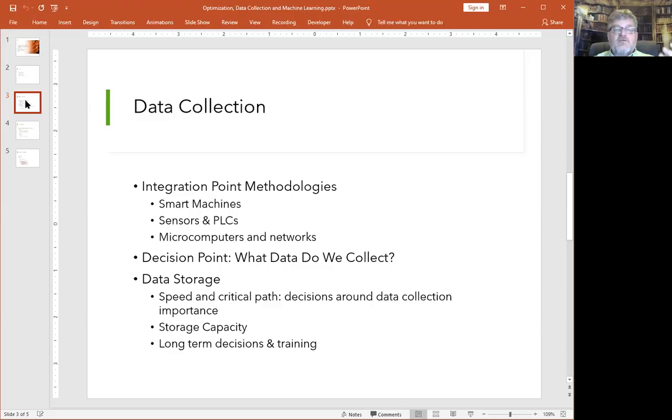So now, 6 months later, I can go look at all the data for every single crimp tool that followed that same exact image. In other words, the image matched, even if it was within specifications of the final product that Tesla required, it may not be exactly perfect. So I could take all the images that match that failed tool image and connect them to all the data associated with that tool failing, and I can do the analysis to figure out why that tool failed.